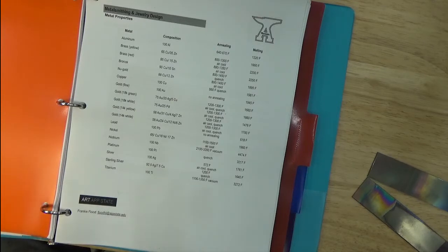If you've ever been to a museum where you see these beautiful silver vessels that are volumetric with multiple components added to them, those were typically formed out of a single sheet, and then it went through a process of annealing, hammering, annealing, hammering, annealing, hammering, until they got the form up to the shape that they wanted. And so you can anneal as many times as you want. There is no limit to that.